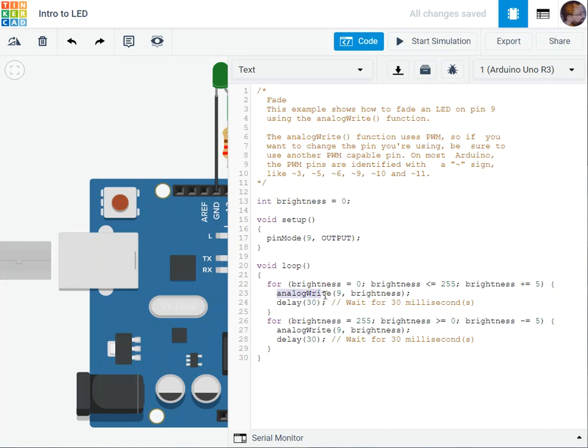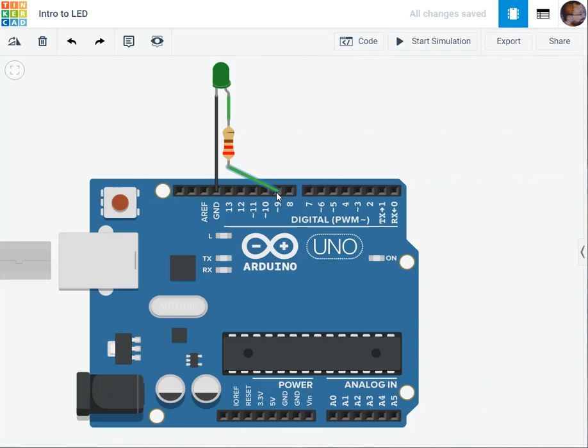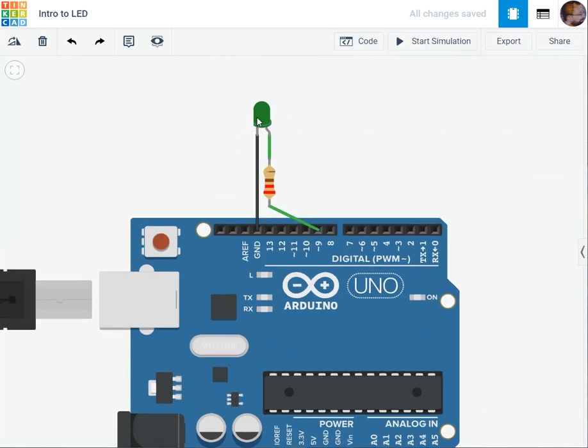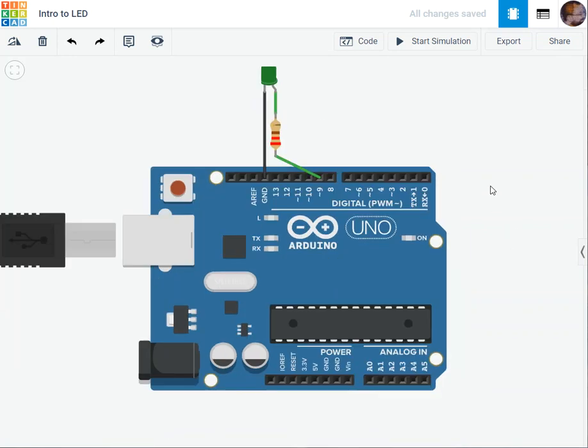Why am I using analogWrite in the code? Because, as I said, here we are not using pure digital. We are using a pulse. I needed it to give me more duration as on. This will be explained later when we do some PWM examples. That's it for today.